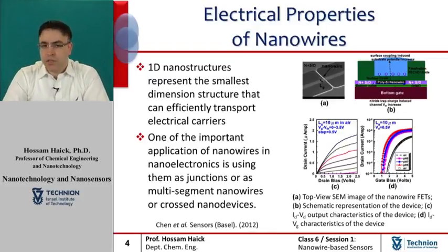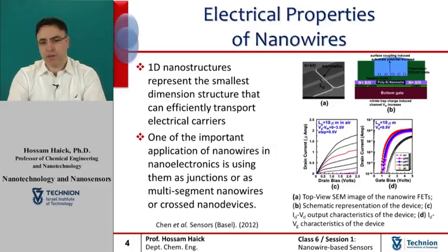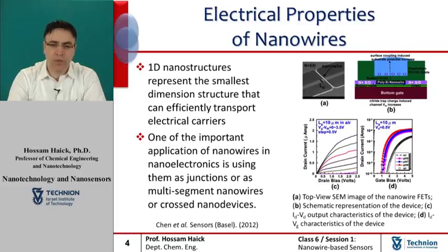We will first start with the electrical properties of the nanowires. A one-dimensional system such as nanowires has remarkable properties and potential in nanoscale electronic devices. They are often configured in field effect transistor structures. Important factors that determine the transport properties of the nanowires include the wire diameter, which is important for both classical and quantum size effects, material composition, surface conditions, crystal quality, and crystallographic orientation along the wire axis of the material.